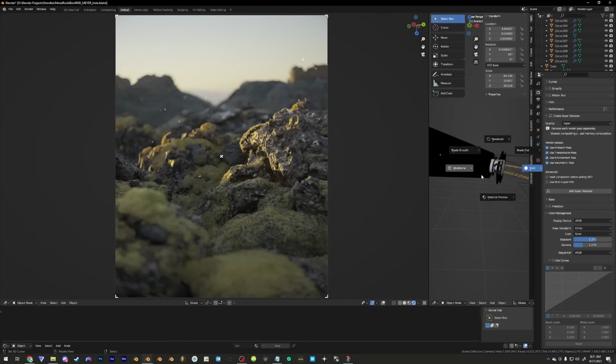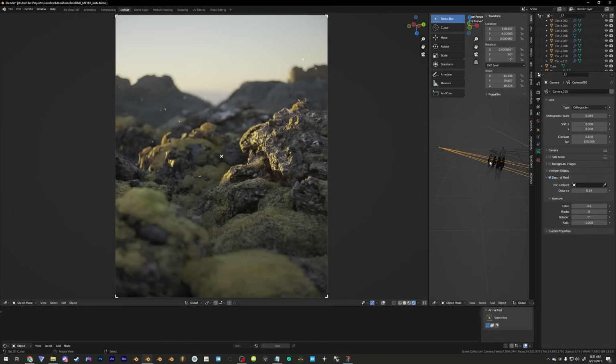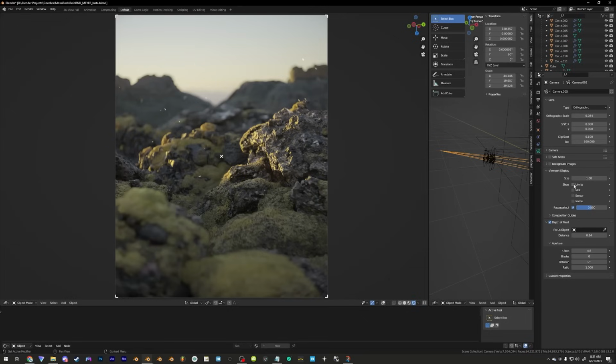As you can see, our camera is extremely far away from the main body of optics here. That is due to the fact that the main optics are significantly smaller than they were when I first modeled it. They are shrunk down so they fit into the scene proportion-wise, and this is what you end up looking at. So we can see the distance sensor from origin is around 0.14, which if we enable the limits, there we go, we can see that this is where our focal plane is, right there, boom, which is the correct distance it would be for a vintage lens like the Meyer Optik series.